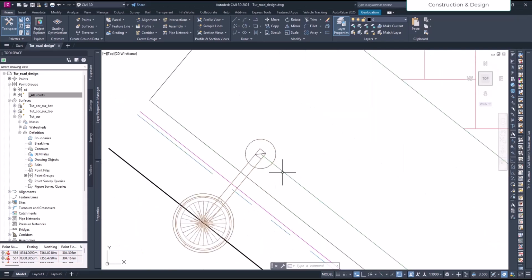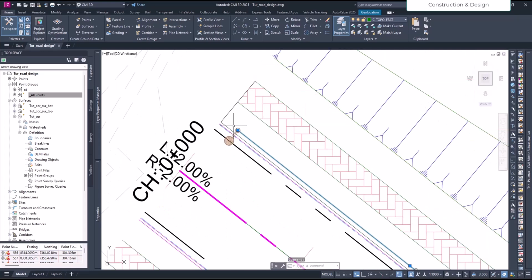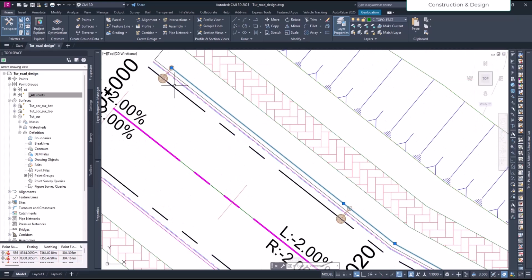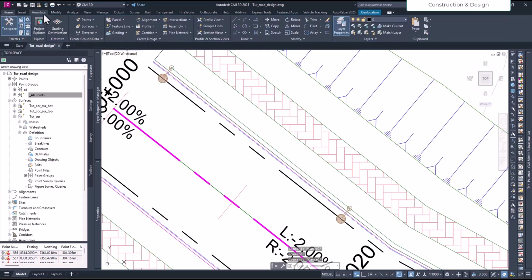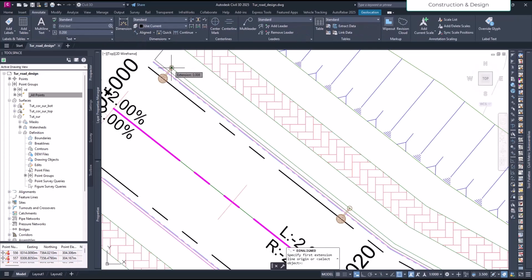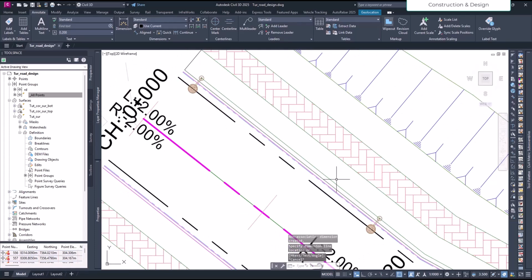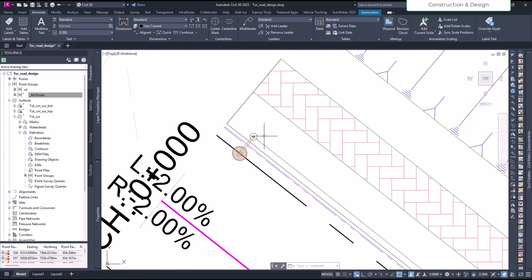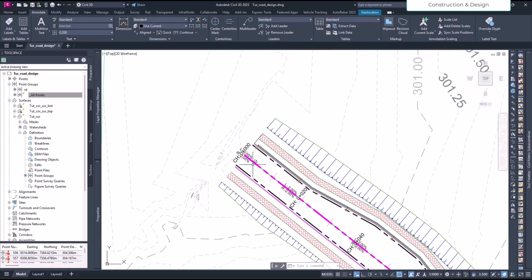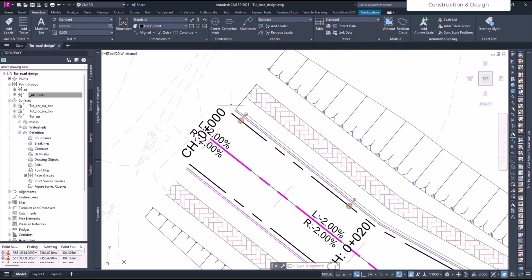Once it's trimmed, I have a starting point, and the distance between these two objects of the array is how much? 15 meters. So let's verify it. Let's align here, just roughly. It's around 15 meters, so it's 15 meters. Now I will create points along this particular line at 15 meters. If I do that, I can get the x, y, and z on this corridor surface, the top of the surface. Then I will get those points.